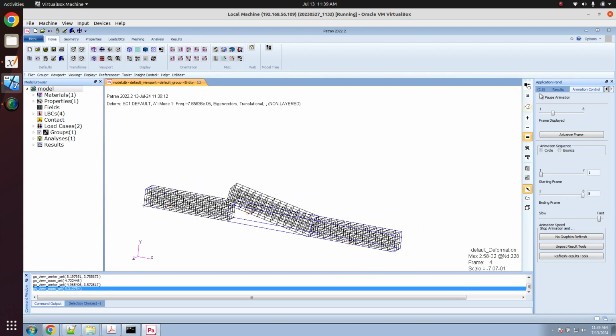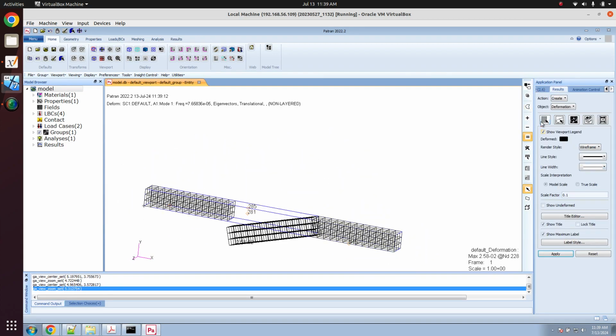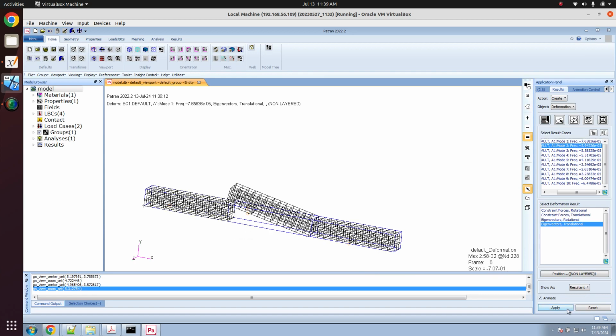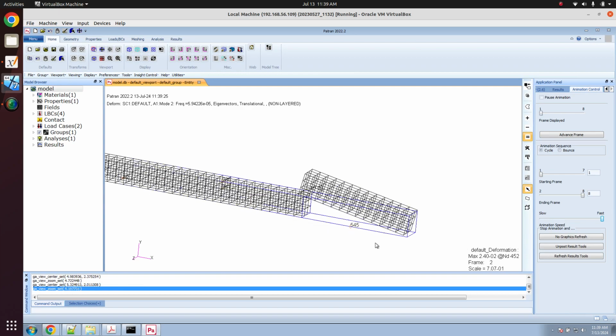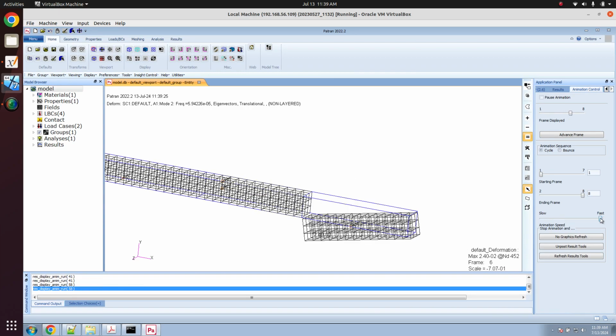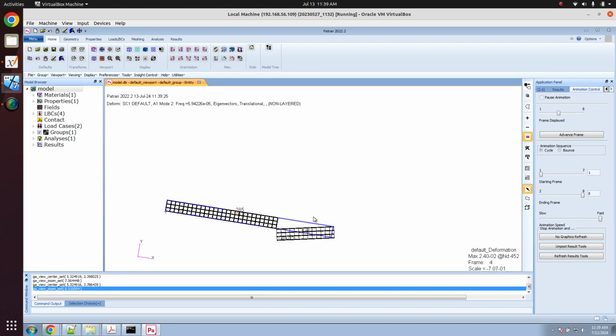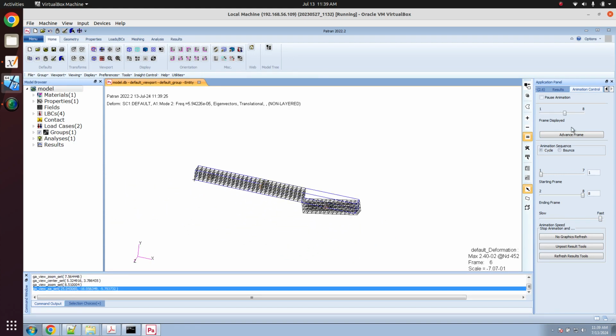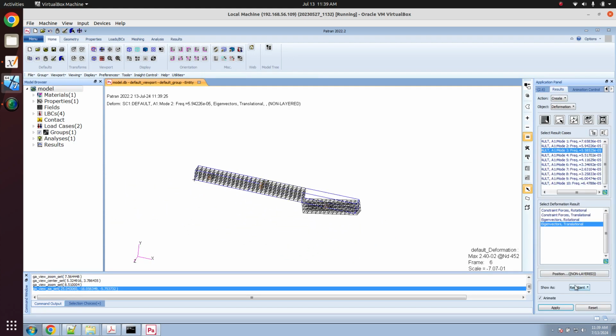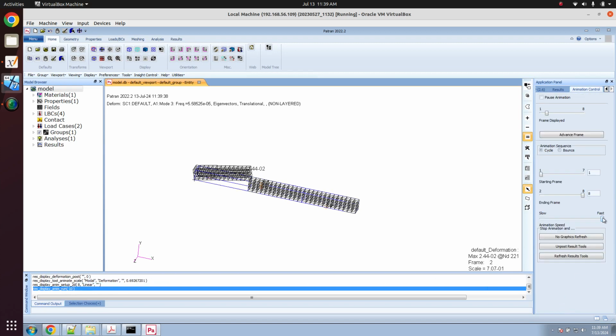So again, this is a detached mesh. And here, let's go ahead and cycle through the other 0 hertz mode shapes. So here, remember there are rollers here. Since there are only rollers here, this is essentially almost like a pin connection, if you will. Let's go ahead and look at the other rigid bodies. Right, so that's also a pin.